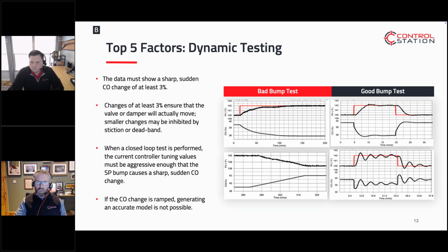Yeah, again, this is fundamental to understanding your process. It's looking at this relationship. If you can understand how your process is reacting, the size of change, the speed of change, the delay of change, it gives you that understanding to be able to go, okay, we can do something with this. Back to if it takes 15 minutes to change the temperature in this process, you won't do it in 5. You do have to be respectful of those numbers. If it can respond in 30 seconds, well then it will certainly respond in 1.5 minutes. You don't have to go to the fast ones to do it.